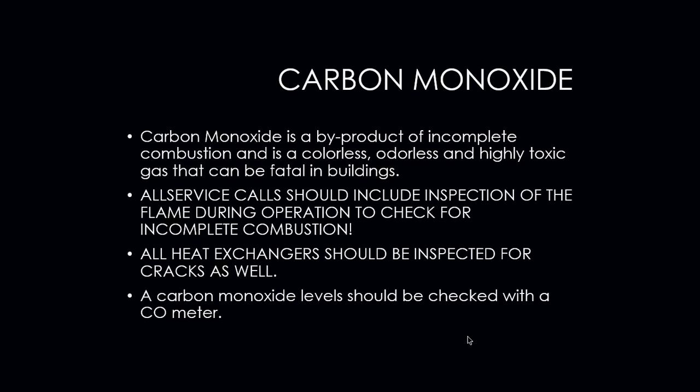Carbon monoxide is a byproduct of incomplete combustion. And it is a colorless, odorless, and highly toxic gas that can be fatal in a building, especially if the concentration gets too high. Anytime you are doing a service call or a maintenance on a gas-fired furnace, you should be inspecting the flame during operation to check for incomplete combustion. You want to physically see what that flame looks like. All heat exchangers should be inspected for cracks as well.